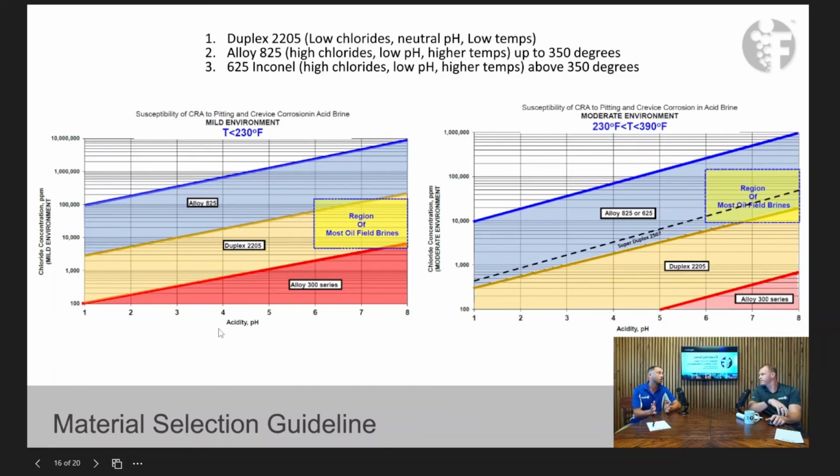That happens a lot. I mean, that's really normal. So if you have operations where you know you're going to do multiple runs of one spool of cap tubing, you can always go up to an 825 alloy, and you're just cutting out that corrosion aspect of it. And if you know you're gonna pull it and put it in another well, it's best just to go ahead and get it, so later you don't have to get another string. I see. Okay, because you can rerun these strings multiple times. Oh yeah, multiple times. Okay, very neat.